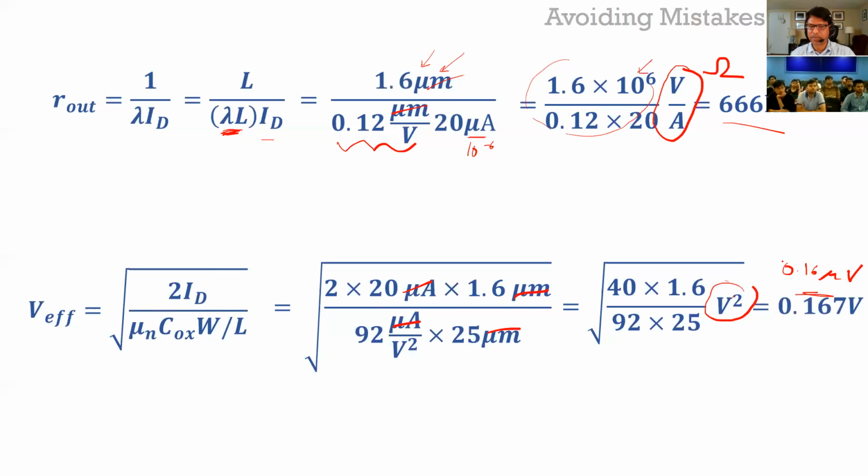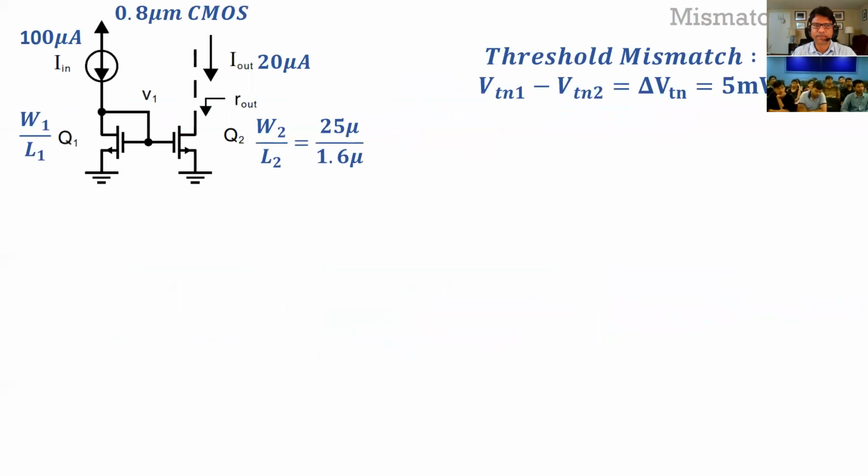Now, typically, again, if a transistor is in active region and you have a sufficient amount of current going, when I mean sufficient, like tens of microamps, then it'll be tens or hundreds of millivolts. Okay, it'll never be microvolts. So if you're getting microvolts, then you're making some unit mistakes somewhere.